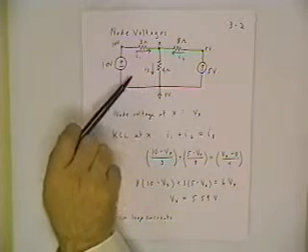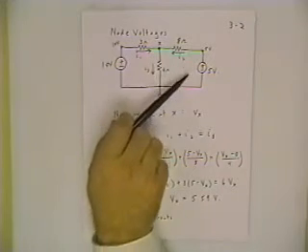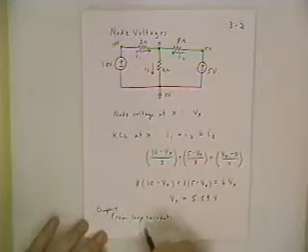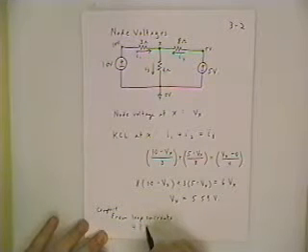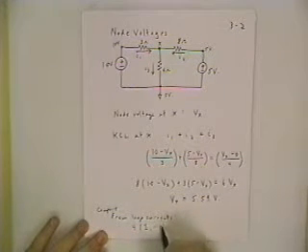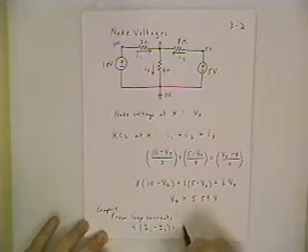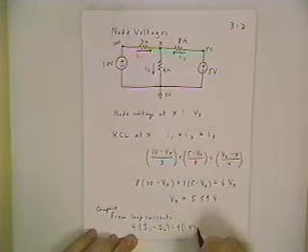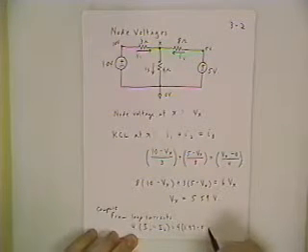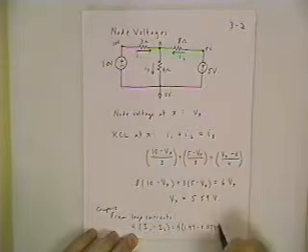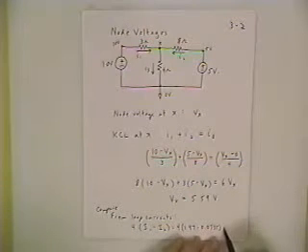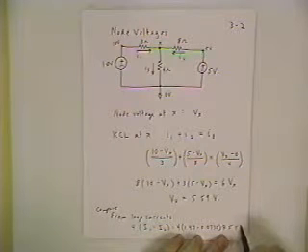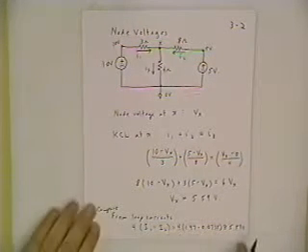Now in the previous circuit we had an I1 loop current and an I2 loop current, so we should get the same result if we multiply 4 ohms times I1 minus I2. And that's equal to 4 times 1.47 minus 0.0735. And sure enough, when you do that calculation, you get something that's within a few thousandths of the same result, 5.59 volts.